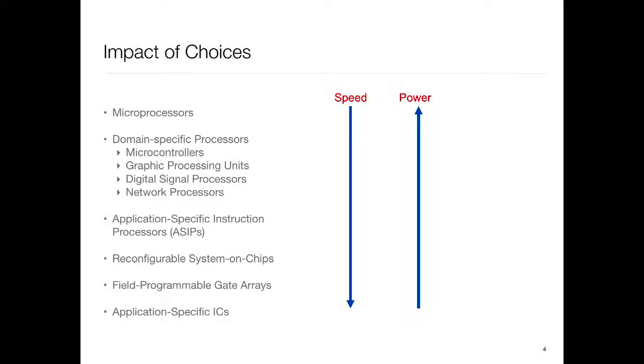Whereas when you hardwire things, if I, let's say, put an FFT module on my chip, and I'm not doing an FFT, then it's lying idle. So that's the disadvantage of a hardwired design. And so these trade-offs can often get subtle, in the sense that it's not obvious where you should reside. Much depends upon details of your particular applications.